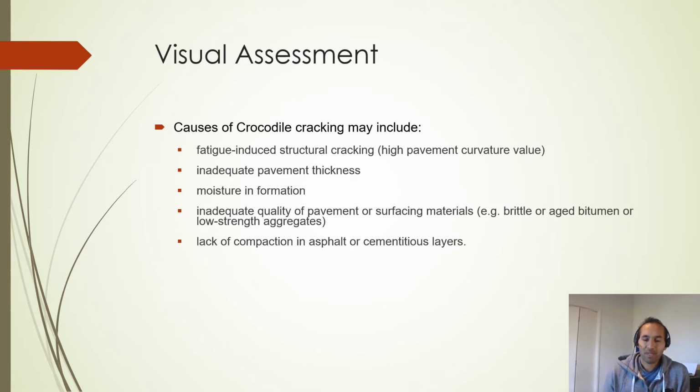One of the issues that can happen is improper compaction. We take care of compaction during construction. There are specifications and quality assurance, but from time to time, we can miss soft spots. We shouldn't, but we do. The aim is to identify soft spots and make sure that compaction is carried out, and there's usually scale A, scale B, scale C testing in VicRoads. You want to ensure that the material is constructed as specified. If it has been, then there shouldn't be issues, but we find that a lot of times it isn't.